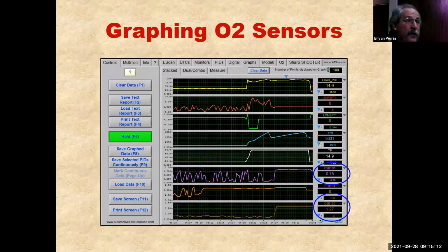So if this vehicle was tested on a new platform today, it would have never failed. It would have never been fixed. However, this vehicle was done prior to 2015, when we still gave them a tailpipe test. We can see that it did fail badly. We have a rear O2 sensor that, given the code we have, certainly makes sense. If the rear sensor can't go to low voltage, then the computer is going to kill itself trying to take away fuel to make it go to low voltage.